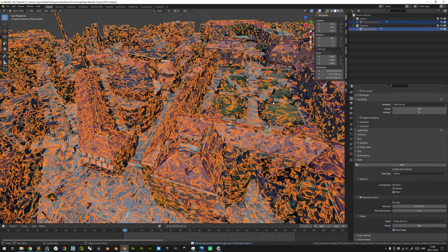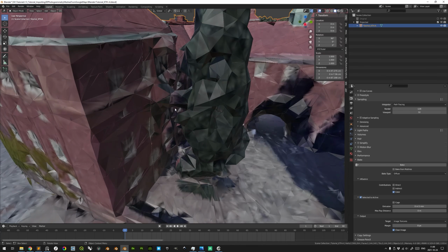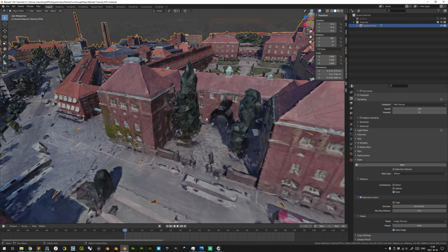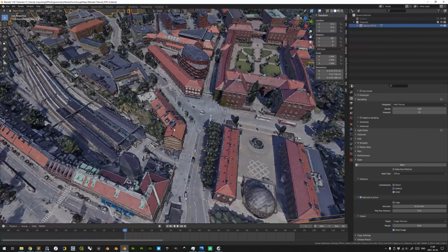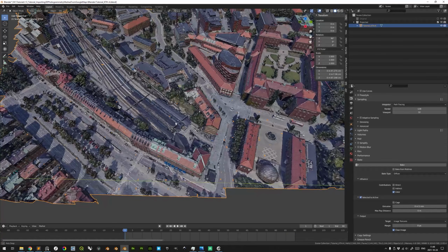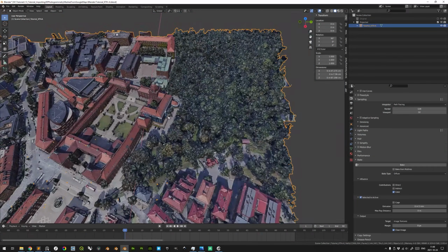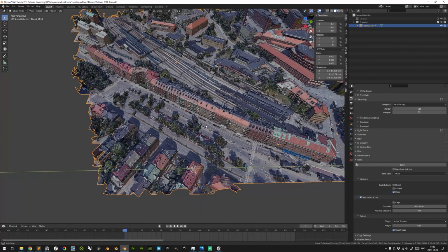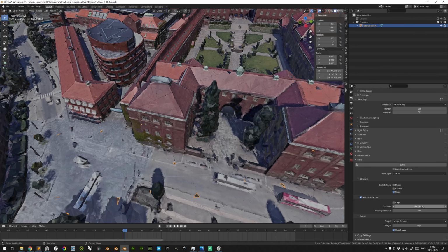All right. Let's see here if we hide the original. Yeah, now you see here that it's not as excessive. It's a little actually, but it's less than before. And do we have any black splotches? Not that I can see. We could bake one more time and reduce the extrusion amount even more.